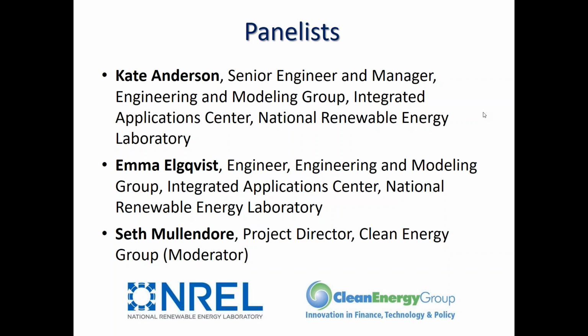Yeah, so right now what I would recommend is that we do give sizes that are not necessarily commercially available. Like I think you saw in Emma's demo, there was a 194 kilowatt system instead of a 200 kilowatt or something like that. What you might do is get the optimum system size out of the model, and then on the inputs page you could go back and set the minimum and maximum sizes of each technology to something that's close to that but is commercially available, and then run the analysis. Then you'll get outputs for something that is actually commercially available, but you'll know that it's close to the optimum size that REopt recommended. Great.